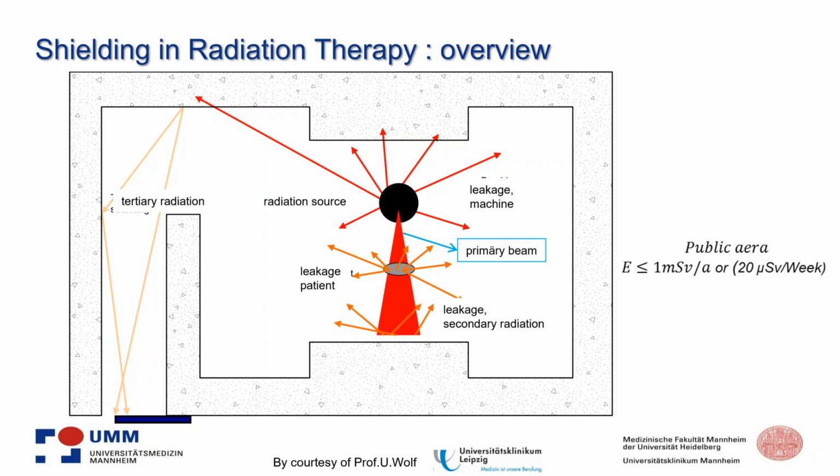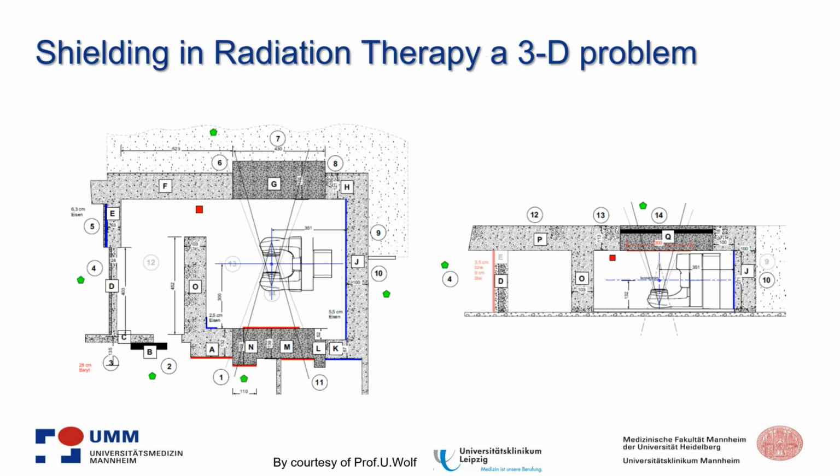If you have mazeless treatment rooms, you have to compensate for the maze by a thicker door. You have the comfort of a shorter and more comfortable way into the room, but you have to work with thicker doors.